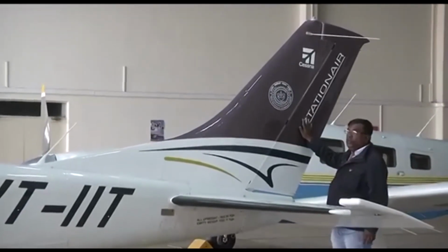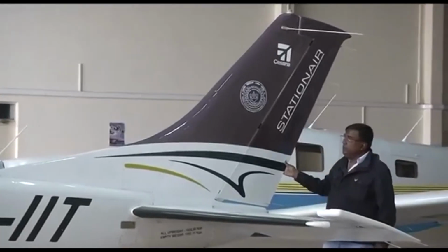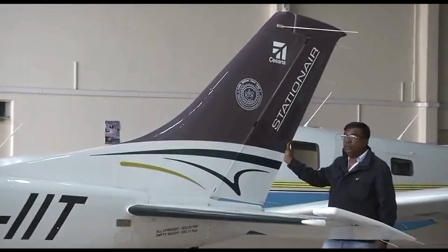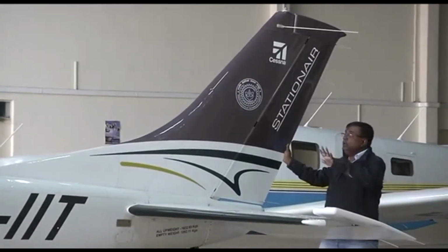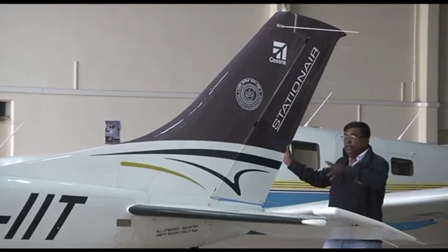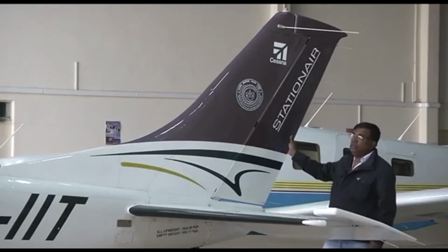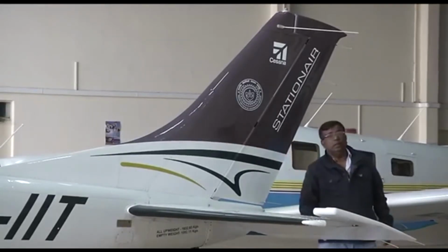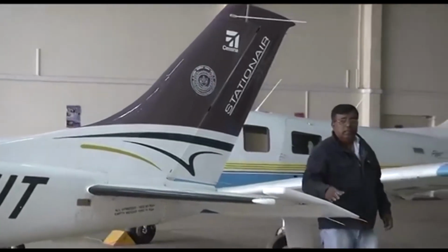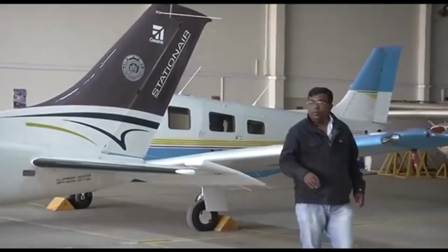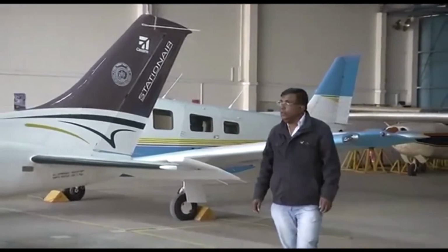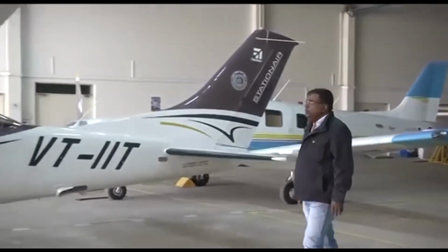So the rudder has to be very powerful, because if it doesn't have enough power, then if the airplane has gone into a stall and is spinning, the aileron will not be effective. So at that time the rudder will be used to counter the rolling. You could hear the background sound of an airplane taking off. So we always love it. We want this sound to be there all the time.